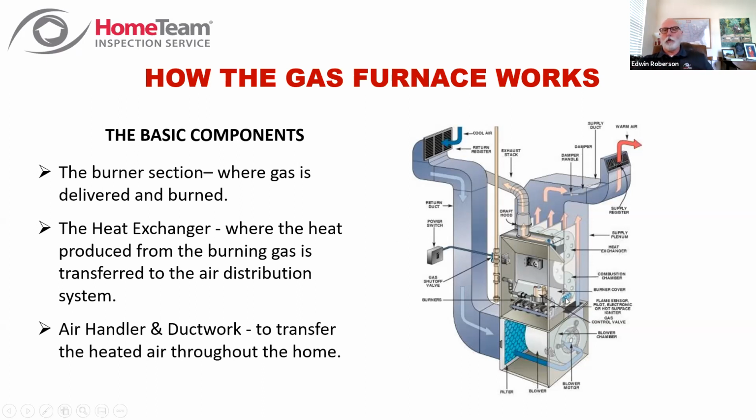That's where your gas is being burned from the burners. The heat exchanger then is where you're drawing air from the area, and you're sucking it through here with a combustion fan across that heat, and your combustion products are traveling through here and then traveling out the flue.